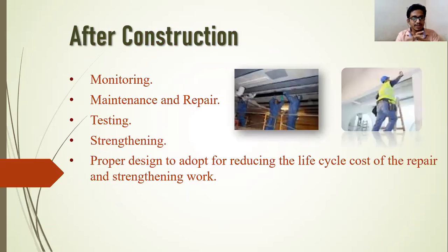So after construction, there is monitoring of structures, then maintenance and repair of structures, then testing as well. Again, we have to do some tests. We cut some cores of the specimens from any place where it creates a problem or where cracks come. We do some testing there, and based on the amount of degradation or deterioration, we have to do strengthening work also.